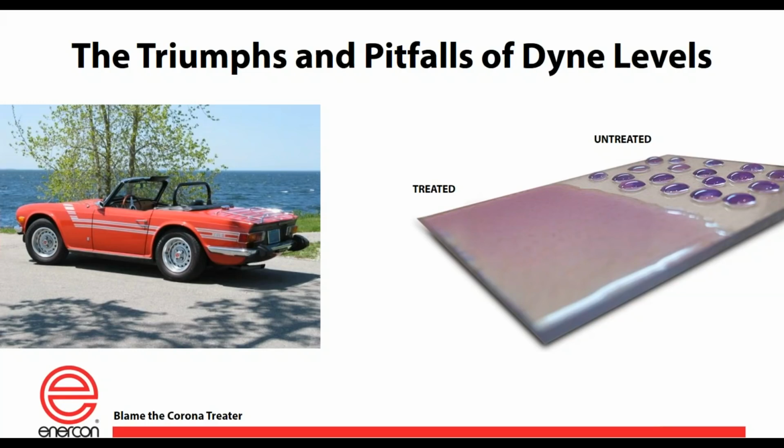Basically, what the Dyne test is doing is giving you an understanding of the surface of the film's ability to wet a liquid. Dyne solutions are made up of two solvents, ratioed in a certain proportion to each other, and that will then allow the solvent to be a 36 Dyne, a 38 Dyne, a 30 Dyne, a 50 Dyne, whatever the number is on that bottle.